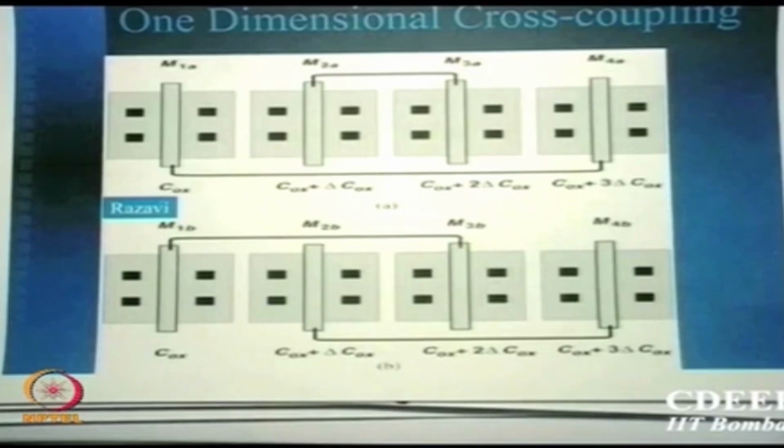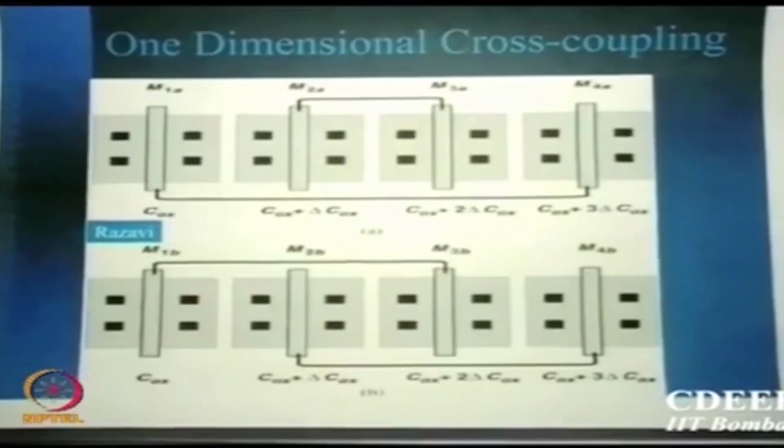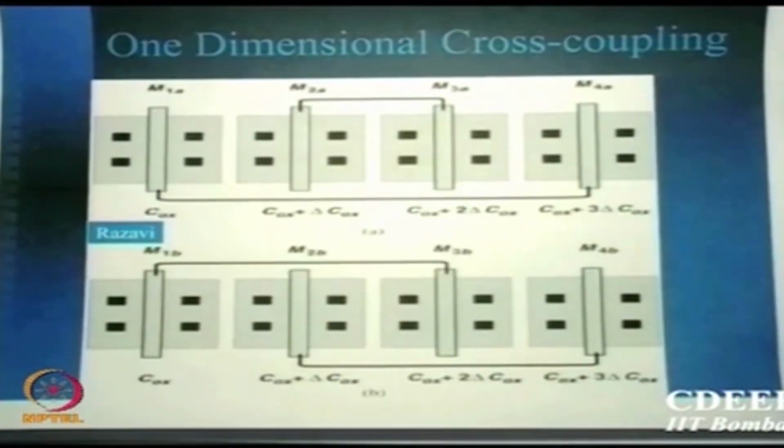Is that clear? So now all that I am trying to show you is why analog layout is a little different. Virtuoso, which is the famous layout editor in the case of Cadence, if you are an analog designer, there is a separate shell in which you work. If you are a digital designer, you work in a different shell. The reason is, both have Virtuoso, but they are different Virtuosos. Okay, so one is actually designed for analog, the other is designed only for digital hardware. So please use it, do not use Magic, because Magic has no connection with anything, neither analog nor digital, it is only a graphic editor.